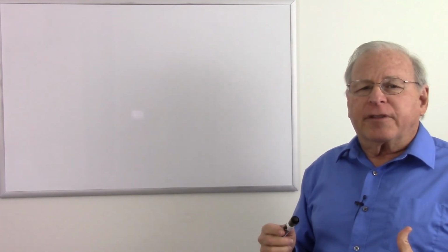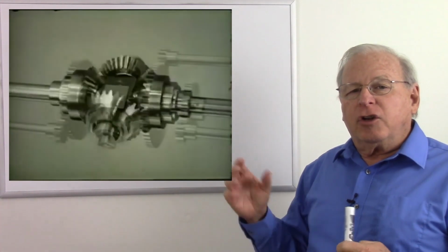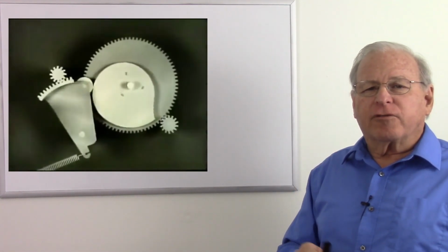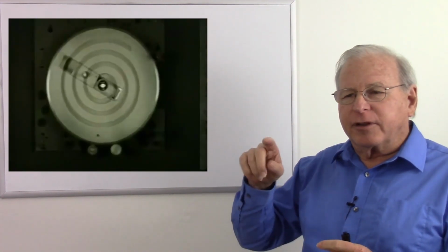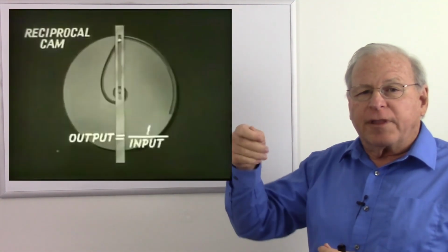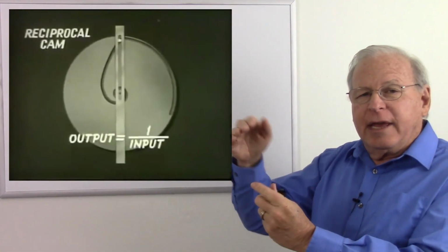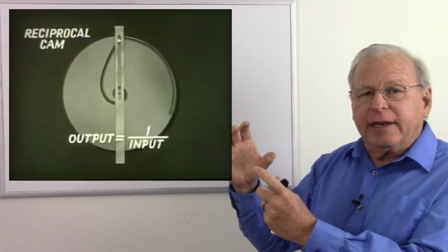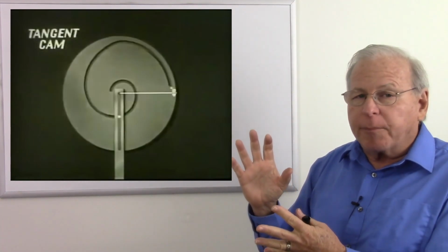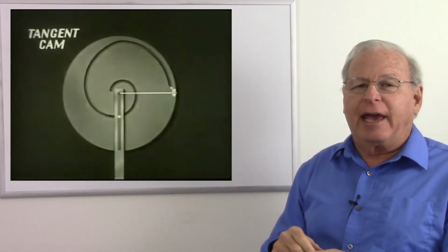They used a number of different things to do the calculations, such as differentials, which could do a subtraction operation. And they had cams and followers of all sorts of different shapes, spiral-shaped cams and other weird-shaped cams, which were rotating discs with either notches inside them or the edge was the proper shape and the follower would follow that edge, and you turn that cam one way and the follower would be pushed out or in and give you a solution based on the rotation. That would be a mathematical operation based on the shape of that cam.